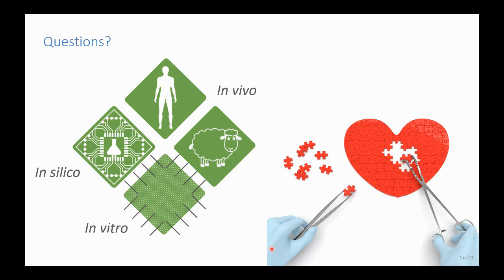But you're absolutely right that the hyperelasticity baseline disregards any time-dependent effects in our tests. The way we do our biaxial tests is we apply the same strain rate as what is there physiologically. So we use strain rates equivalent to the movements between diastole and systole in the body, and we disregard the rest.